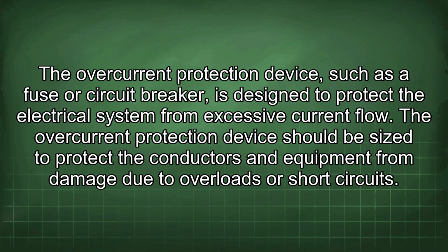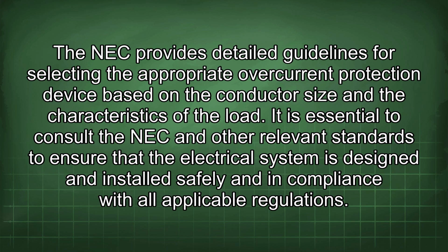The overcurrent protection device, such as a fuse or circuit breaker, is designed to protect the electrical system from excessive current flow. The overcurrent protection device should be sized to protect the conductors and equipment from damage due to overloads or short circuits. The NEC provides detailed guidelines for selecting the appropriate overcurrent protection device based on the conductor size and the characteristics of the load. It is essential to consult the NEC and other relevant standards to ensure that the electrical system is designed and installed safely and in compliance with all applicable regulations.